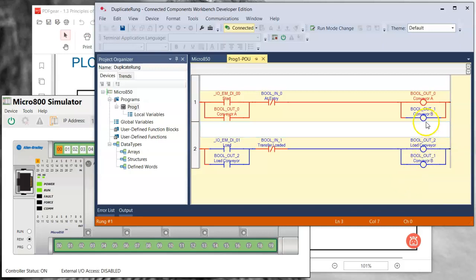In that it's actually saying you should be off. So rung 1 quickly said you should be on, but instantly when it got to rung 2, solving rung 2 logic, it said you should be off. So they kind of oppose each other. And therefore that's where the destructive bit terminology comes in, because they kind of cancel each other out or destroy each other in this case.